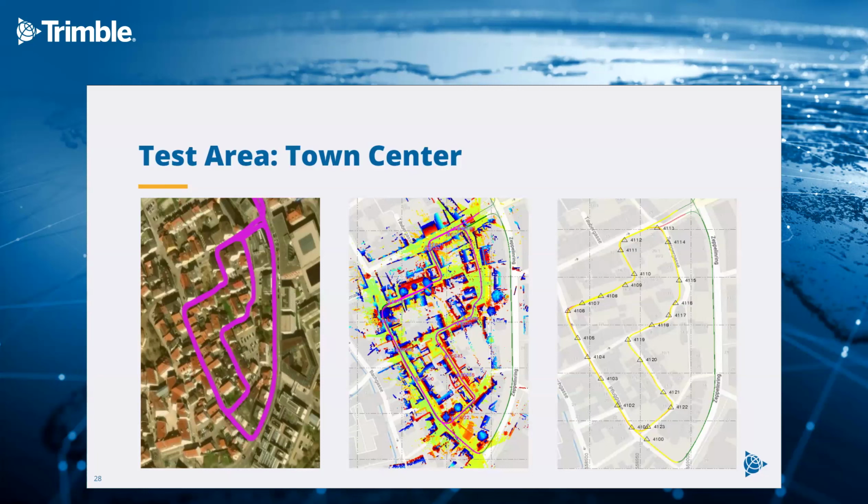So in terms of the ground control points that you can see here, both 3D and vertical points were distributed over the entire area. And these points were surveyed through the establishment of a dense reference point network using GNSS technology and a Trimble terrestrial 3D laser. So basically, the entire area was scanned in a static mode before to lay out all of those ground control points. All of those surveyed points are referenced in the European Terrestrial Reference System 89, in short ETRS89 frame.